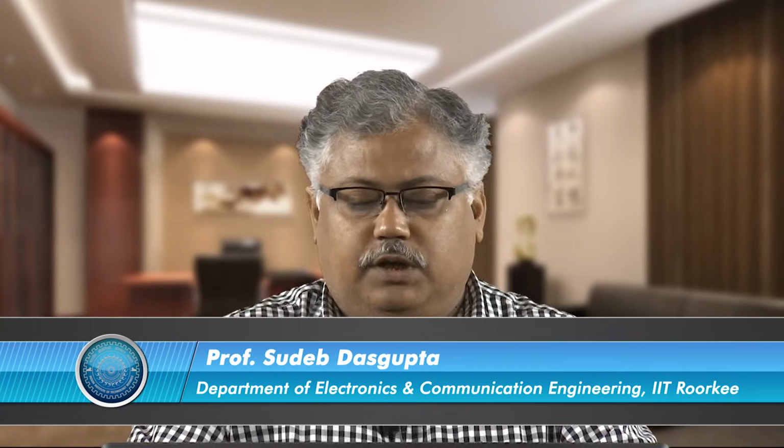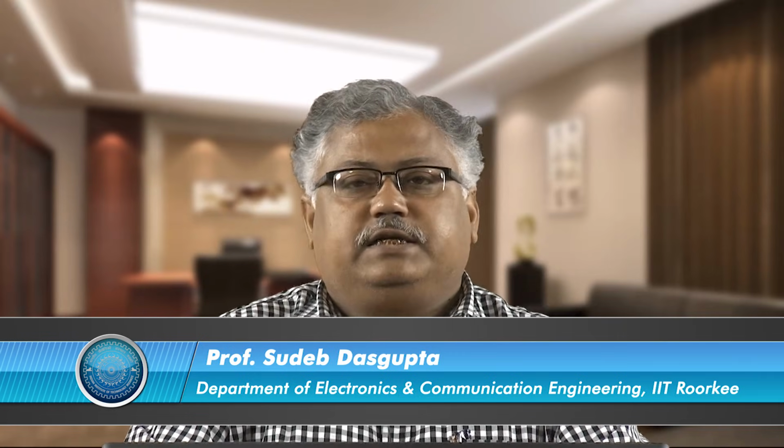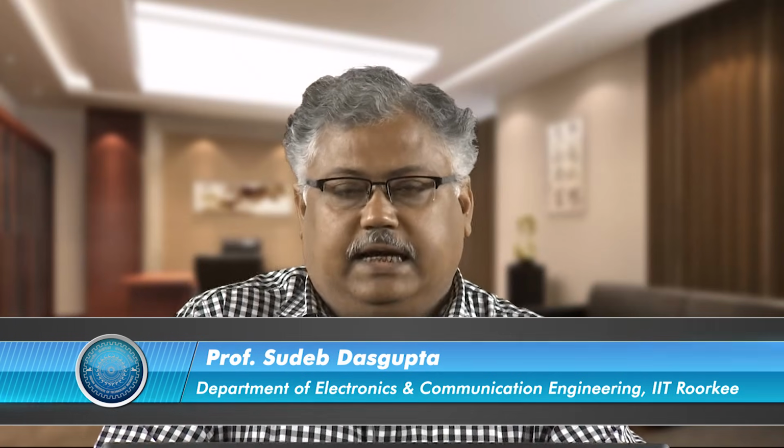Welcome to this next module of the NPTEL online certification course for CMOS digital VLSI design, and we start the second part of the inverter. In the first part we have seen the static characteristics of an inverter, how do you draw a voltage transfer characteristics, which is VTC, and then how do you extract the switching threshold and the noise margins from the VTC.